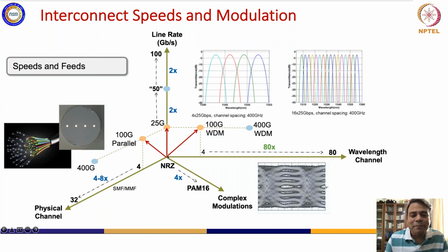You can use multiple physical channels, so that when you connect two systems together, if you go in your normal RJ45, there are 4 twisted pairs, right? Why is it called UTP, twisted pair? So, unshielded twisted pair, there are 4 pairs of copper, so you can have more parallel lanes to increase the bandwidth. Okay? Or when you're going optics, you can start multiplexing multiple wavelengths into an optical fiber. So all of these parameters have certain limits, and limits are very much related to current technology, physics.